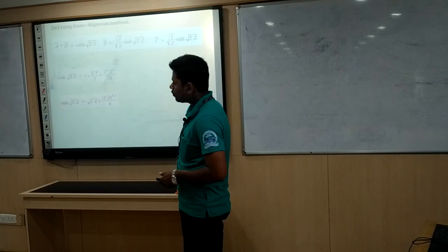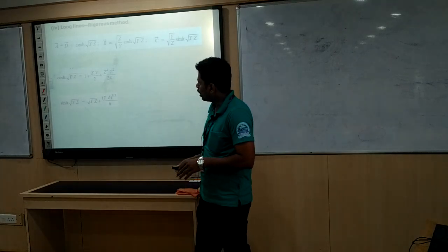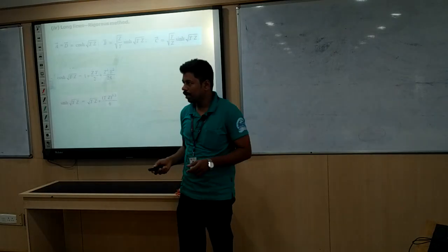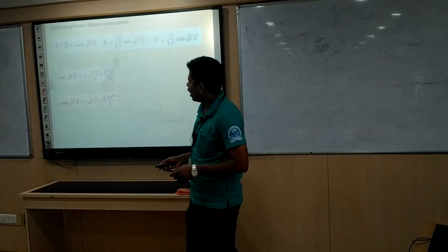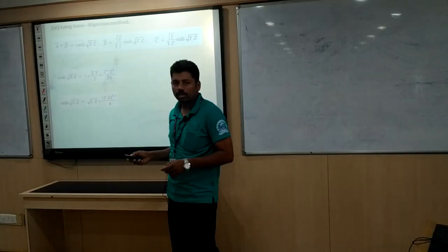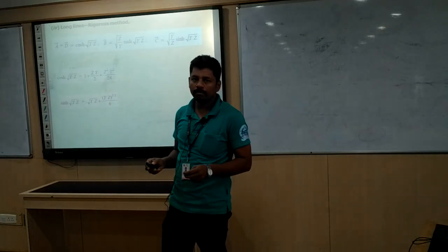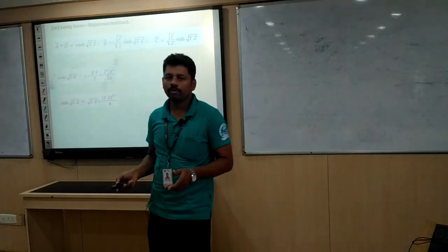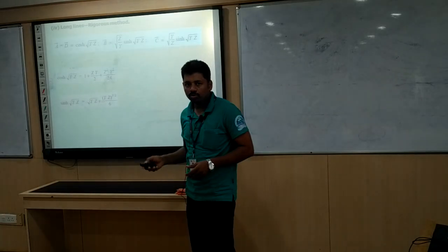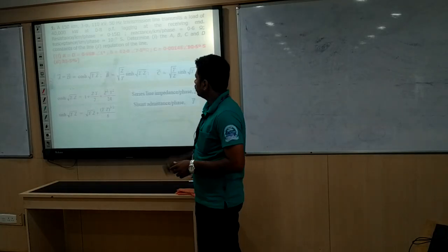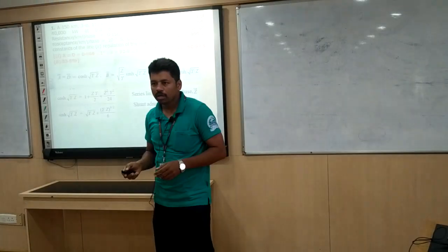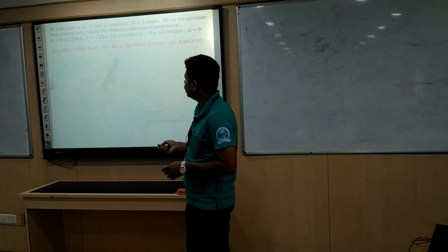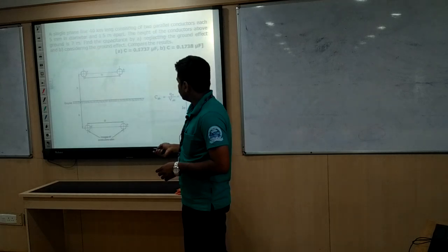In the long transmission line, the equation is already of the form Vs equal to A VR plus B IR. So if you compare these two, the conditions A equal to D and AD minus BC equal to 1, all those are satisfied, and we get the expressions for this. That is why we are able to use this for the long transmission line also. Some numericals we are not going to discuss now, just to apply how to find the corresponding voltage regulation and efficiency for the various cases.